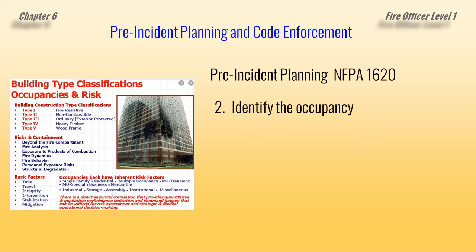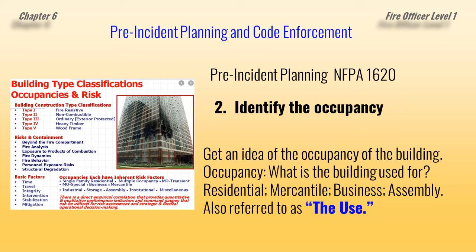Next, we're going to identify the occupancy. When we talk about the occupancy of a building, we're asking, what is the building used for? The occupancy is also called the use. Is it a residential building? Is it a mercantile building where they sell things, a strip mall, a store, a Lowe's, a Home Depot?